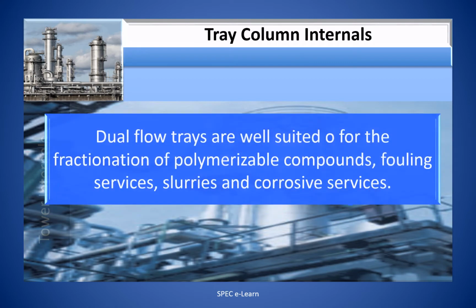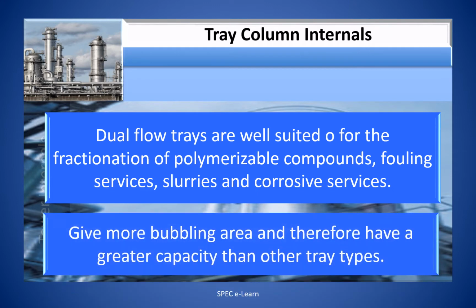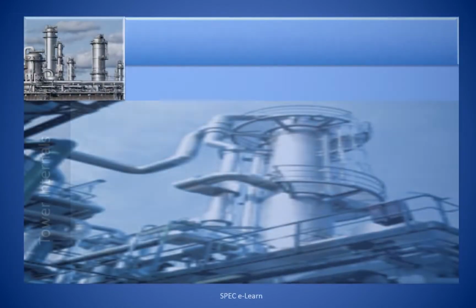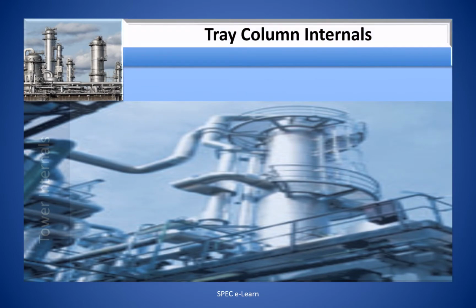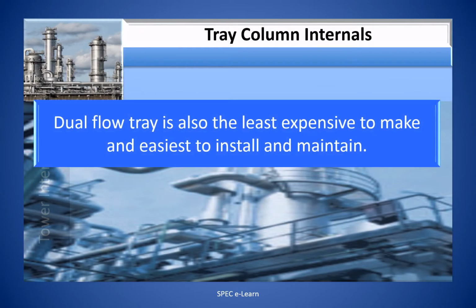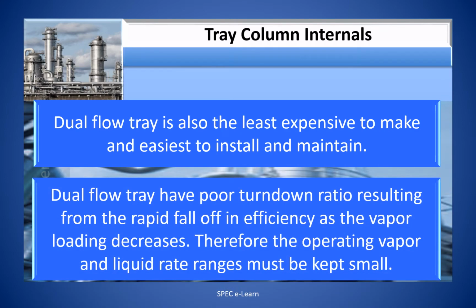Dual flow trays are well suited for fractionation of polymerizable compounds, fouling services, slurries, and corrosive services. They give more bubbling area and therefore have a greater capacity than other tray types. A dual flow tray is also the least expensive to make and easiest to install and maintain.